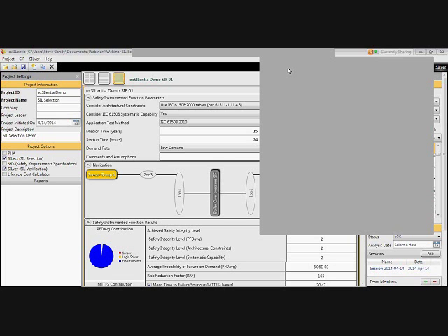You can put that in, but certainly you can see if you've got tight shut off, and also you're doing regular proof tests. If you can claim that your coverage and your proof testing will get you to that point, then of course that's entirely up to you. But we tend to say that you cannot achieve 100% proof test coverage.